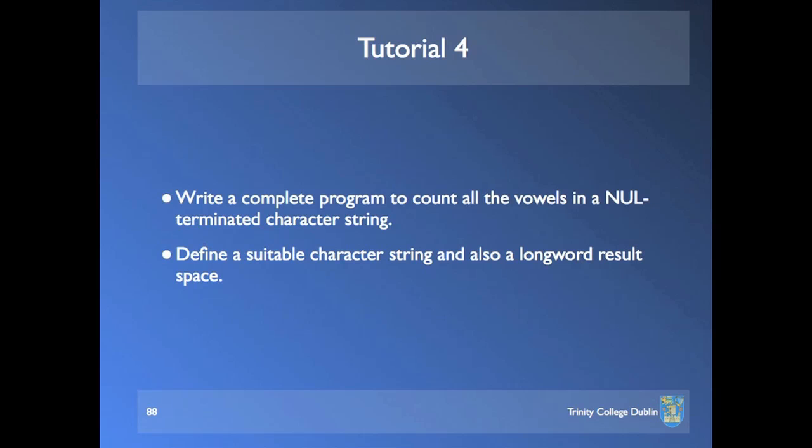But it doesn't necessarily mean, as at the machine level you might say, that the numbers are negative. It depends on how you, when you're writing the program, are interpreting them. If you're interpreting them as unsigned numbers, then you simply ignore the fact that the N bit is set. You just say, I'm not dealing with signed arithmetic, therefore the N bit has no particular meaning, nor does the V bit, the overflow bit. They're just of no meaning, and so I won't use any conditional branch instructions that have them as part of their conditions.